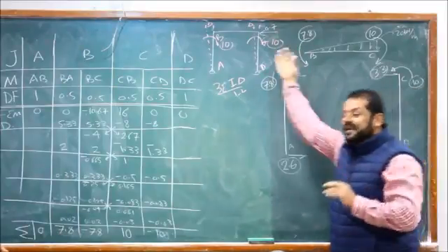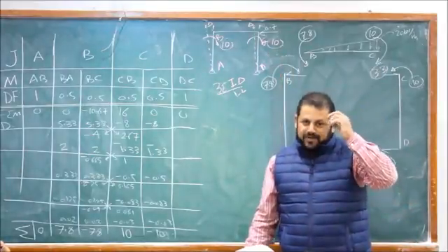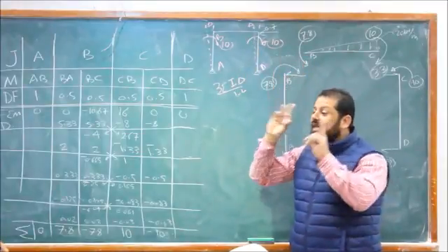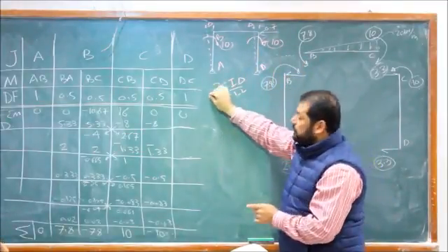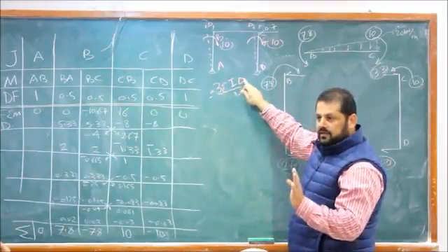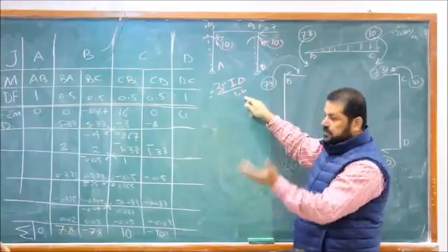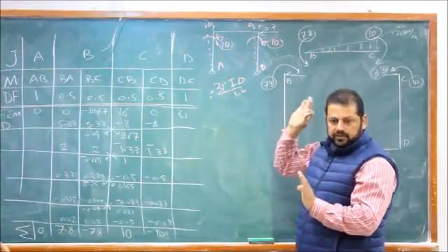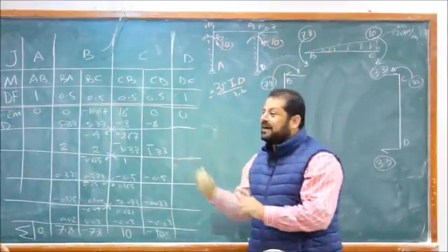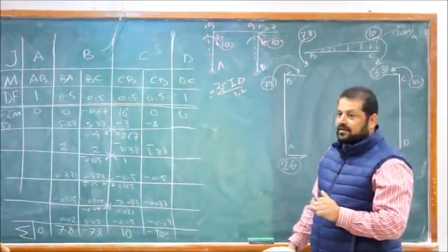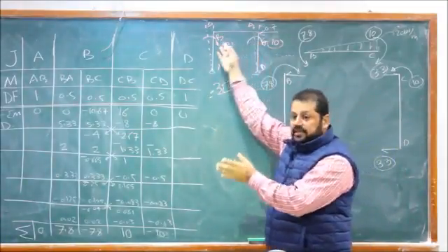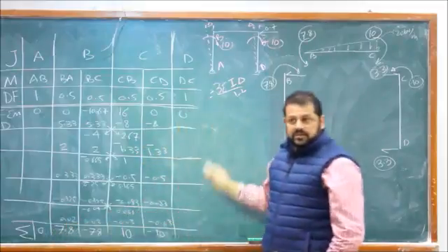So we will assume 10. Listen, we will assume 10 for the fixed moment, not delta. Delta you can calculate now. We will assume the fixed moment to be 10. So if you want delta, you can calculate delta. It's 10 times L squared divided by 3. Yeah, we can do it, but we will assume it 10. Then we will solve how much the 10 will give us in fixed-end moments. So from the 10 here, we will calculate fixed-end moments.